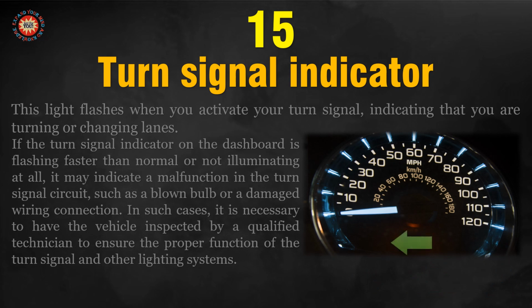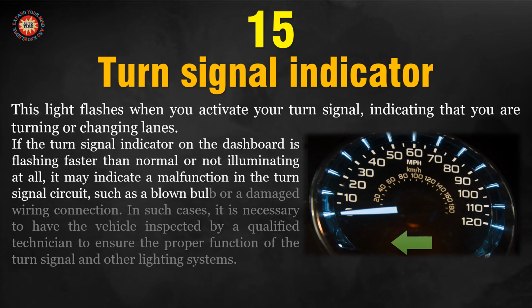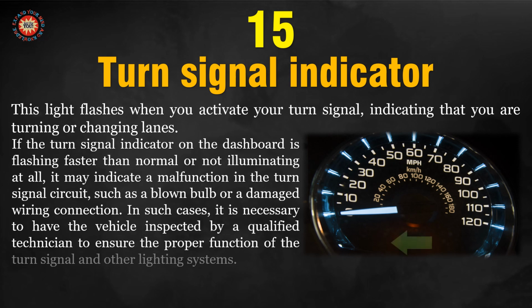Symbol 15. Turn signal indicator. This light flashes when you activate your turn signal, indicating that you are turning or changing lanes. If the turn signal indicator on the dashboard is flashing faster than normal or not illuminating at all, it may indicate a malfunction in the turn signal circuit, such as a blown bulb or a damaged wiring connection. In such cases, it is necessary to have the vehicle inspected by a qualified technician to ensure the proper function of the turn signal and other lighting systems.